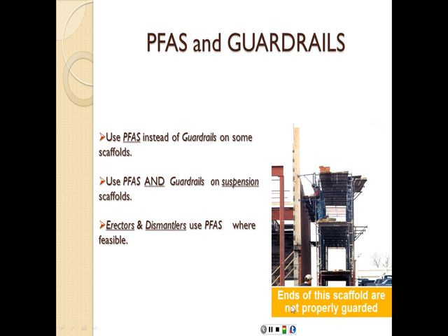You can notice here that the ends of this scaffold are not properly guarded. We don't have any guardrails on the sides of that scaffold, so it's not properly guarded.